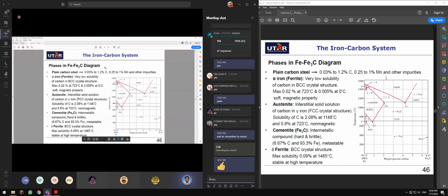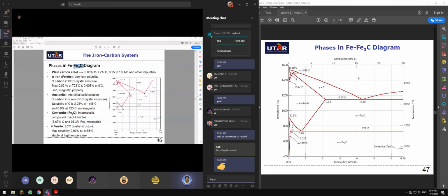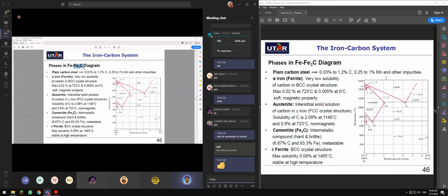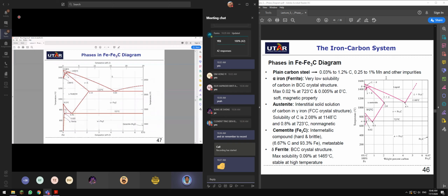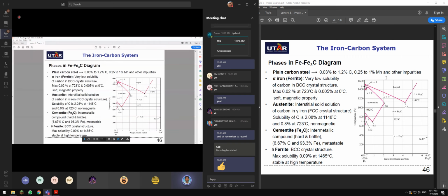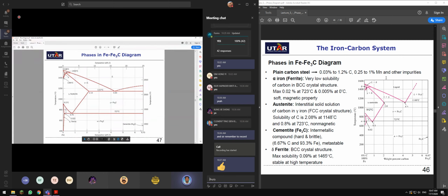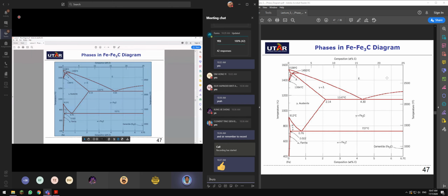That is the reason why there's a lot of confusion. They don't call it iron carbon phase diagram. They call it iron cementite phase diagram. You can call whatever name you want. Same goes for R and S, the lever rule. You can name it whatever name you want. But here there's also a confusion among societies. Some of them will call it iron carbon system, but the carbon here is not 100%, it is 6.7. Some of them will call it iron cementite phase diagram just because it is not 100%. Okay, fair enough.